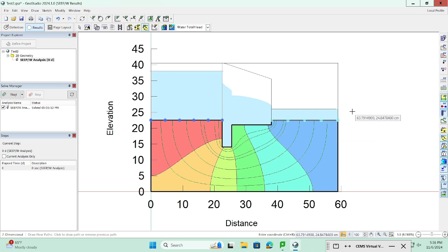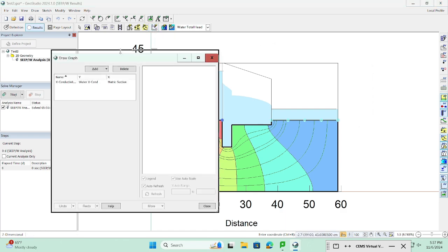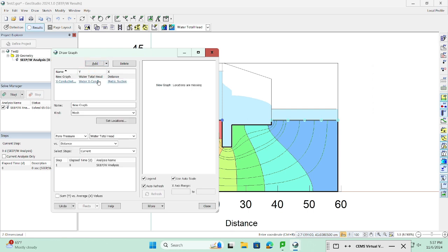What else should I show? You can very simply go to graphs, and then go to add, and you can name this graph. I'm going to make it discharge. Okay, discharge, and choose this to be flow, water flow, then choose water rate, and choose time. Okay, you can play with all these things.